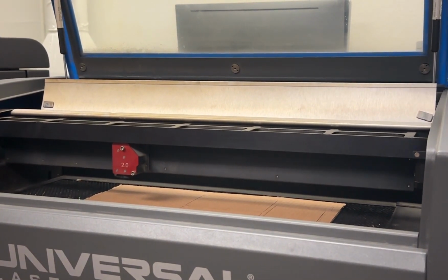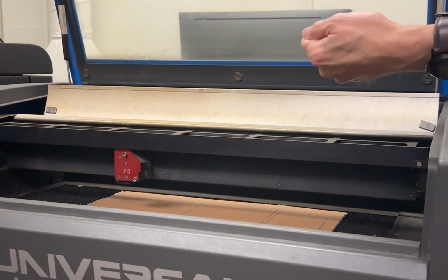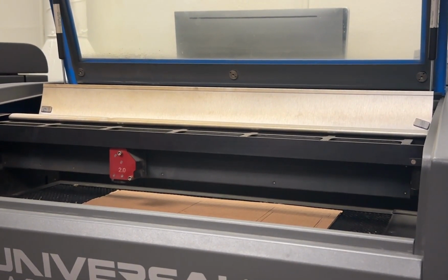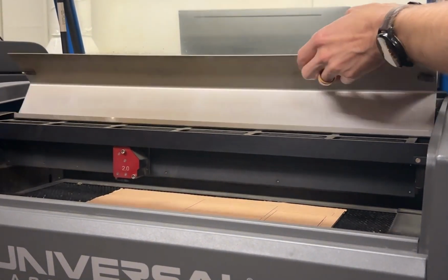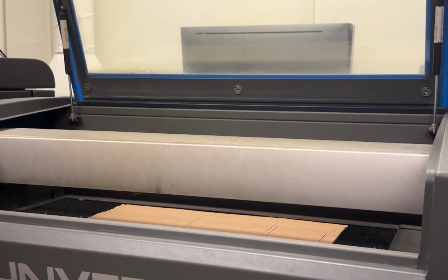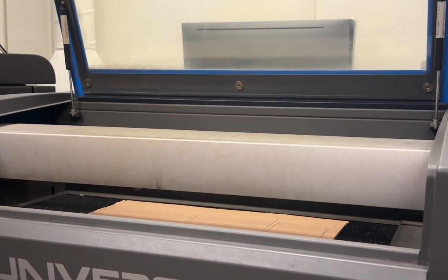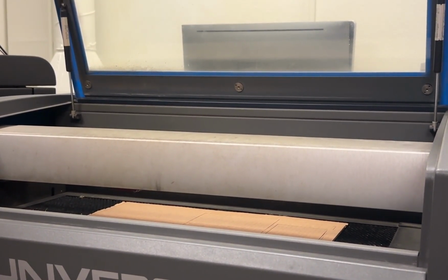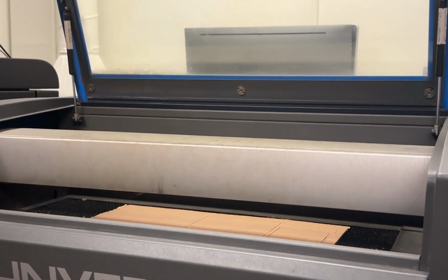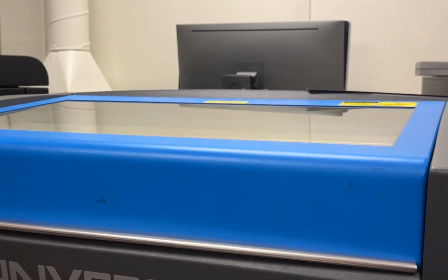And if you have one of the aluminum sort of floppy ones with the cork backing, those are probably the best because you can lay them flat and you can usually get right to the tip of the ruler. Does that make sense? But it is imperative. Otherwise you'll cut it at full power and nothing will happen, right? And it's because of the focus of that laser. I could draw it out, but it's basically a cone, right? And that intersection of the cone is where it cuts. Once it moves past, well, there goes the cone again, obviously inverted. Hopefully that's making sense. I talk in section a lot.